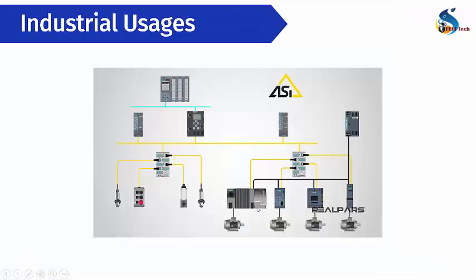Also, when we are talking about industrial usages of sensors and actuators, ASi is a very popular thing. It helps us to reduce physical wiring and components. Also, we can use fewer input and output cards for the PLC. It's connected in master and slave method. Usually, a master can connect with 64 slaves. Here, the sensors and actuators work as slaves.